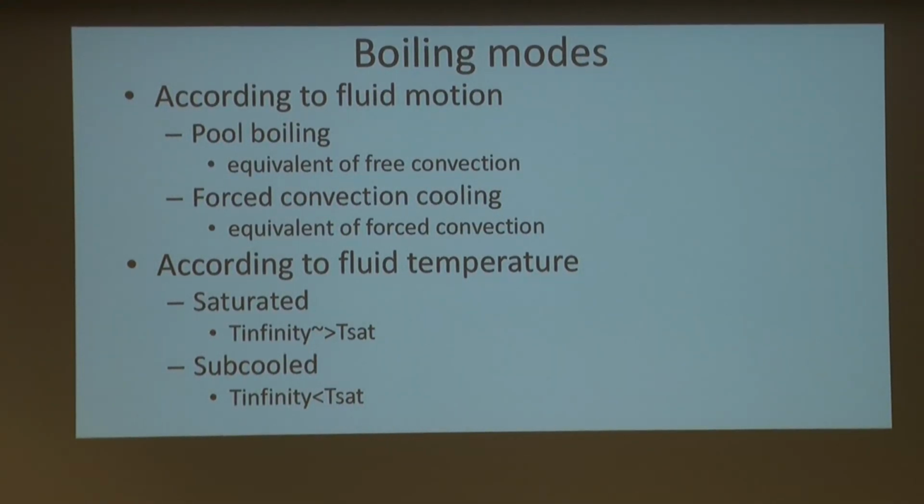But the water around is going to be colder. That's called subcooled. The main difference is this. In saturated boiling, the bubbles reach the surface, but in the subcooled one, the bubbles that are generated get recondensed, because there's no more free energy to have vapor. It goes cold.